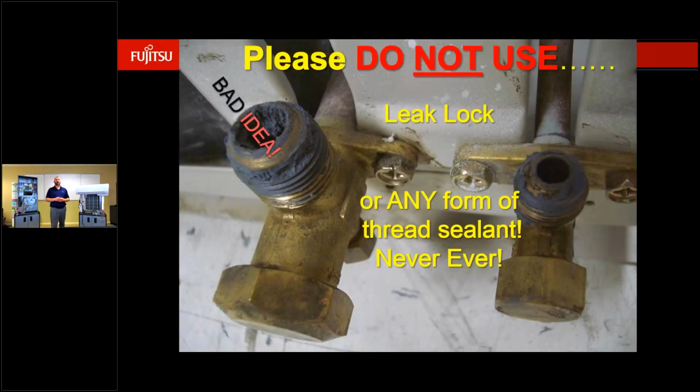Don't use any leak locks, thread sealants, chewing gum, anything along those lines. No Teflon tape. Our brass fittings are machined very precisely, and we do not need any of these products. There are some guys out there that will use 410 refrigerant oil or maybe Nylog or something on those fittings.